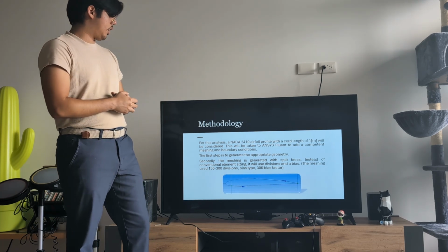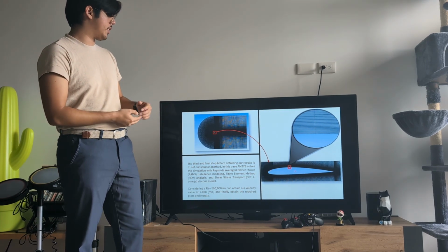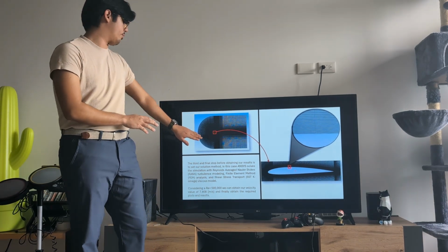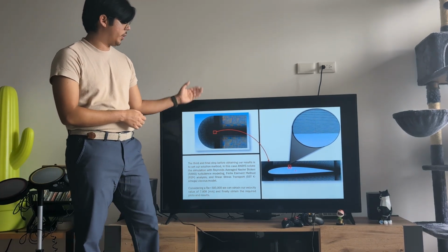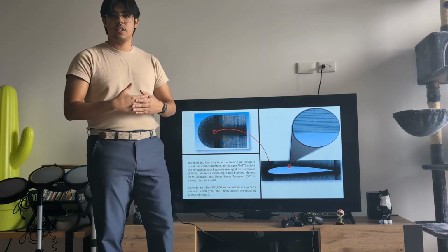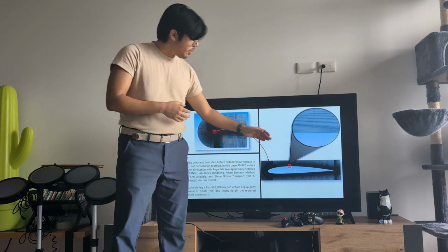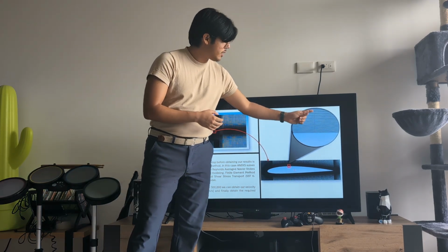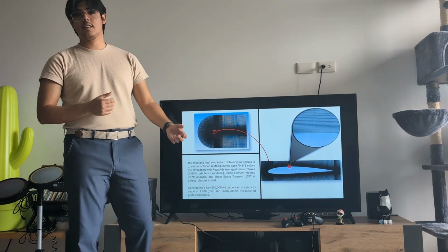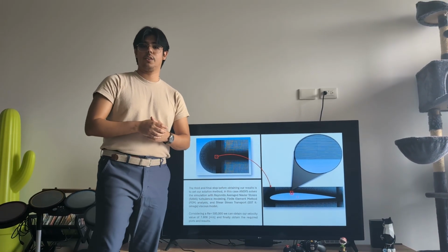Now if you take a look at the meshing, you can see the domain is very finely meshed. You can't really see the airfoil, which is why I made a zoom over here. And even when you can see the airfoil clearly, you cannot see each of the divisions. So I zoomed in even further, and now you can see that the first division is smaller in size than the actual boundary layer of the airfoil.